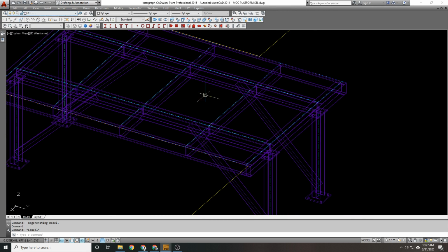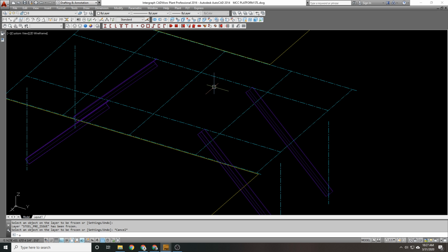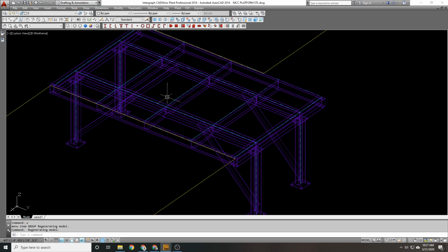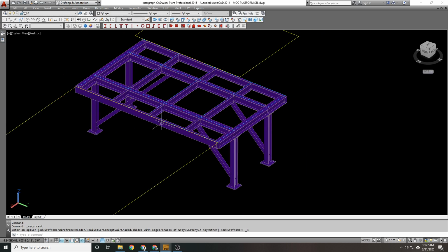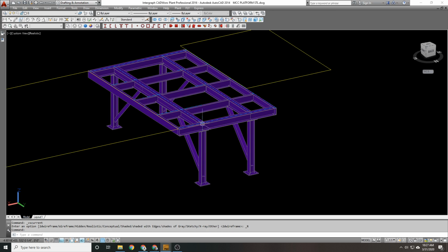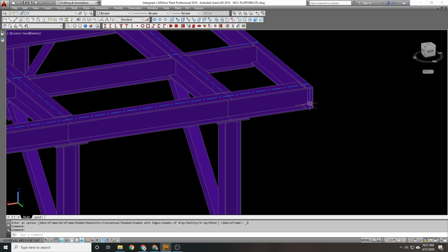So I have it on the layer that I can freeze. If I were to just leave it like the other stuff and I try to freeze it, your center lines would stay behind. So there's my bracing set in place in that direction. I don't think I'm going to need bracing in the strong axis. It's also possible the engineer may want to see bracing on the cantilever, but I don't think so.